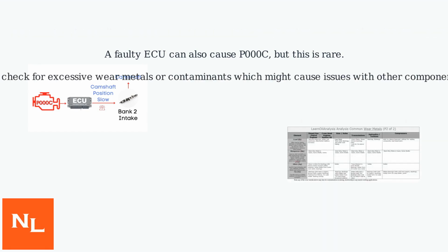Consider performing an oil analysis to check for excessive wear metals or contaminants, which might cause issues with other components that use oil pressure in the engine.